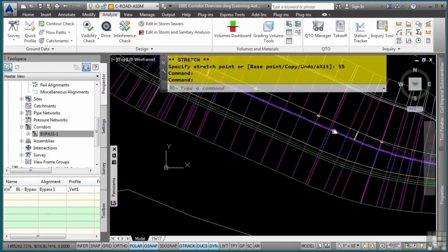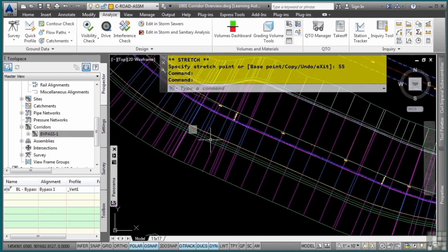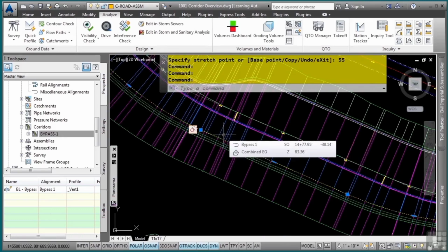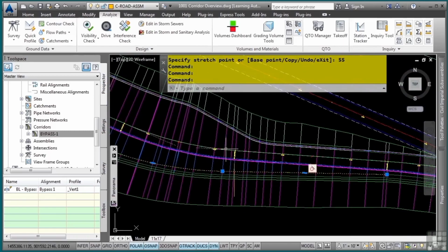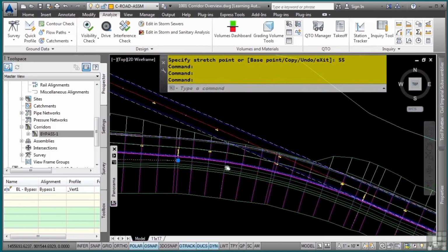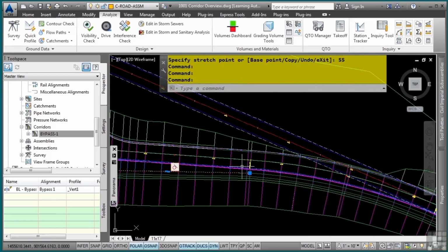One of the other things I have in this drawing is an AutoCAD 2D polyline. But what's really unique and cool about this polyline is that I'm using parametric constraints, just regular AutoCAD parametric constraints to constrain this object. So it'll actually maintain tangency, use coincident points, etc. Any changes to this AutoCAD polyline will update the corridor object as well.